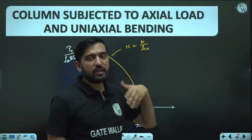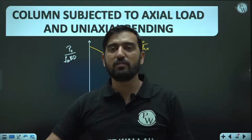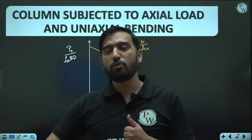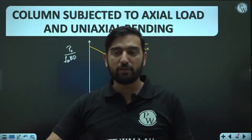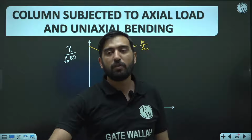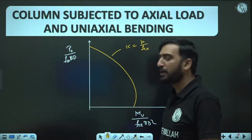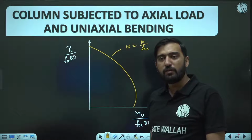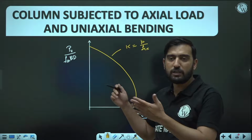So whenever the eccentricity is going to exceed 5% of the lateral dimension, in that case we classify our column to be under uniaxial bending. If both the dimensional eccentricities are exceeding 5% of the corresponding dimension, in that case we will be calling our column subjected to biaxial bending. Okay, biaxial bending. So in biaxial bending, what are we going to do? We are going to design it as a biaxial column, so the same interaction chart we need to read twice.